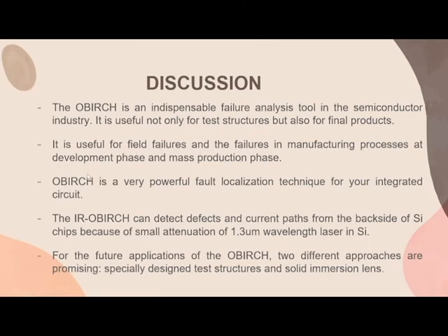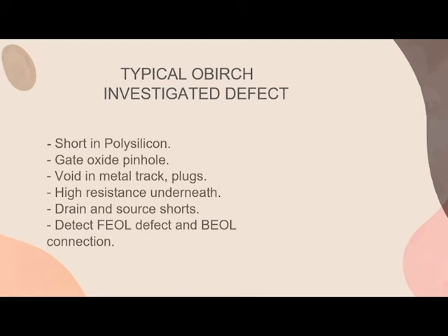Next, OBIRCH is a very powerful fault localization technique for IC, and it can detect or investigate defects, for example, shorts in polysilicon, gate oxide pinholes, voids in metal tracks and plugs, and high resistance underneath drain and source.